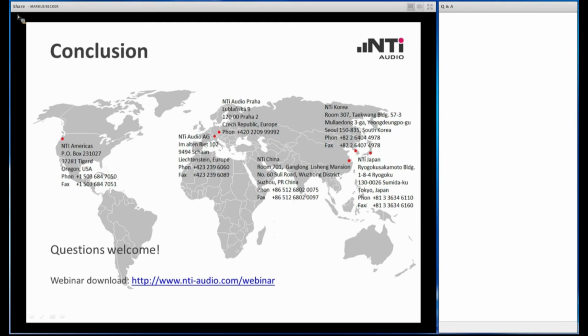A second question regarding the reference microphone, whether the system would also support reference microphones from other manufacturers. The answer is yes. If you already have a high precision class 1 microphone, then you can of course use that and connect it to the system for your application. The FX100 has a built-in phantom power supply and ICP power supply, so it should be possible to connect the microphone directly to the instrument without the need of an external power supply.